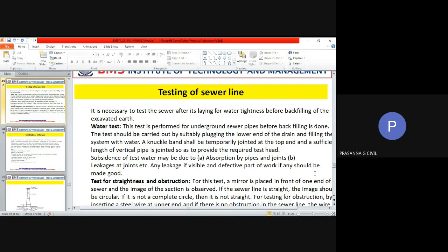Then you have large concrete pipes. The two ends of the concrete pipes will be brought together with a rubber gasket or something in between. And there are concrete collars with a slightly wider dimension than your inner pipes, and then the sealing material will be put in between so that the pipes can be jointed.